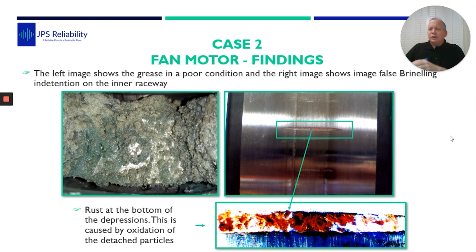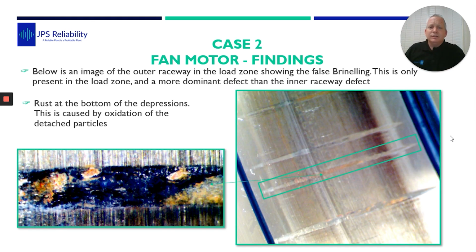But the data was highest on the outer race. Well, when we looked at the outer race, these dents, they were like craters, you could feel them. You can see here on the picture, we got 3 or 4 together. So that motor had sat there, no one had turned it, and there's vibration in the plant, and it's shaking down, and it's shaking down, and it's causing the brinelling. And there's a very slight movement in the rotor, just moving that bearing there.